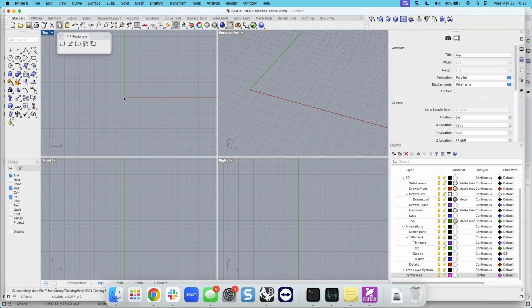So in CAD, you draw your building 500 feet long. You draw your table 8 feet long. And then you scale it in the viewport on the layout. So I want you to get used to that. When we're drawing here, we're drawing full size. So when I type in 18, whether it's 18 feet or 18 centimeters or 18 inches in this case, that curve is 18 inches. It's full size in real world values.